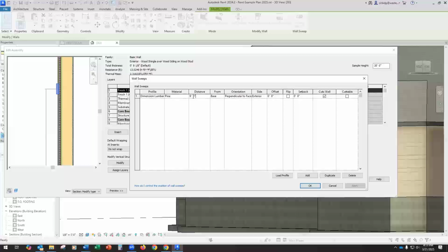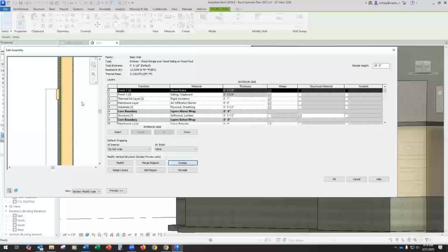So I'm going to just show you how we could move that down. So if it's 5.5, it's going to be 2 3/4. So that would be 8 foot 9 1/4. So let's try that. So there you see that profile now is at 9 feet, just like the other one was, except now we have control over what it is.